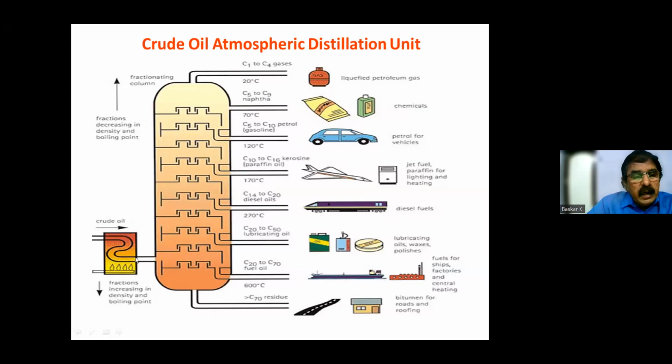And it is entering at a temperature. Okay. The lighter ends will be in vapor form. They will try to escape through the chimney trays to the top. Okay. Now we'll concentrate on the bottom one. The heavier ends will come to the bottom. And here we are maintaining a different temperature profile. How do you maintain this different temperature profile in a single tower? That we'll see later.